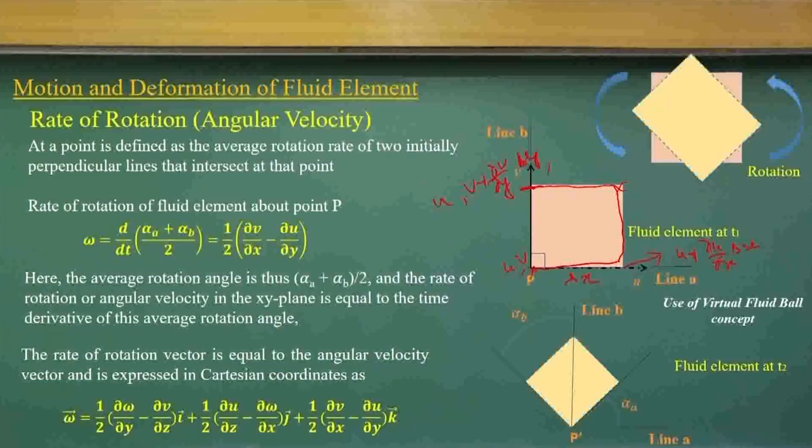Now, when you take a fluid element, at the 4 corner points we have velocity variation because of these velocity components. Because of this velocity component and this velocity component, the fluid particle is going to rotate. Is it correct? The velocity component v at these locations will try to rotate it. The velocity component u, the gradient, the relative difference of velocity components, will make it move.